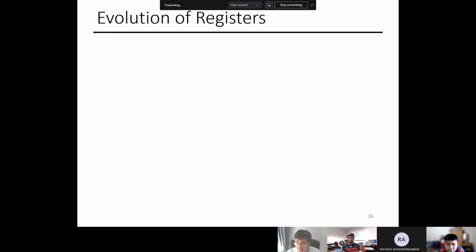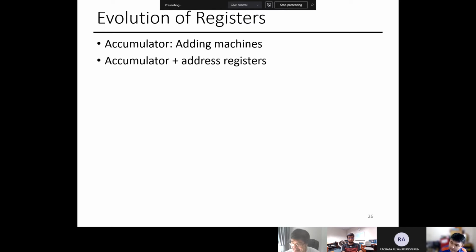And there's also the evolution of registers, which I want to put in a historical context, because back in the day, you only had things like I can add up, count down. These are called accumulators. They are really simple to design, but annoying to use. Because they're annoying, once we had advances in digital circuits, we could use things like an accumulator plus a way to specify the address, to tell where in the memory we want to access. So that's the next evolution.